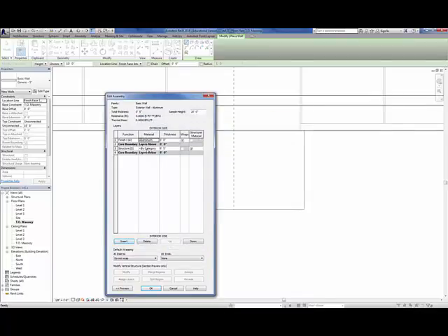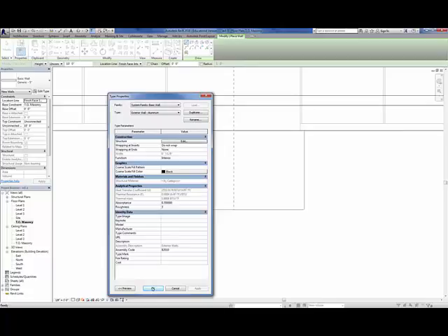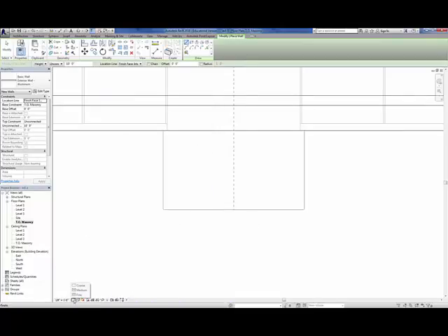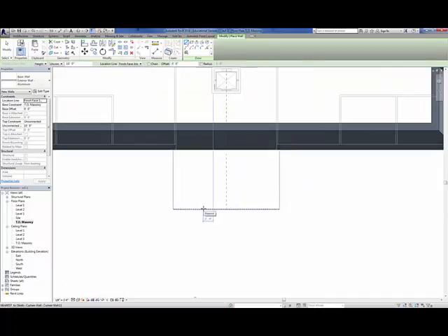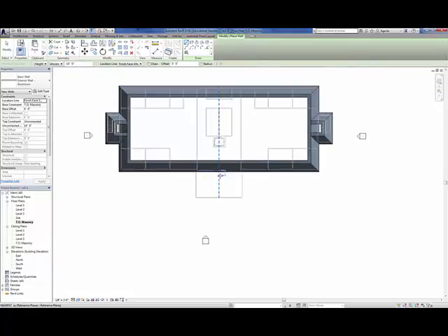The structure below that we're just going to leave alone, so it'll just be generic. We're going to set it at 2.5 inches. And we'll set the thickness of the aluminum at 5/8 of an inch. Okay, I'll hit OK. And everything looks good, so we'll hit OK again. Let's see, I'm going to update our view to medium and change it over to shaded so I can see what's going on. So right now, I realize I can only see the roof because we don't go down far enough.